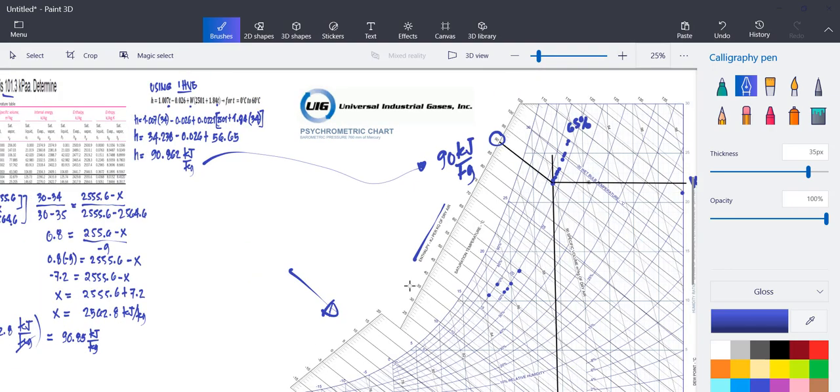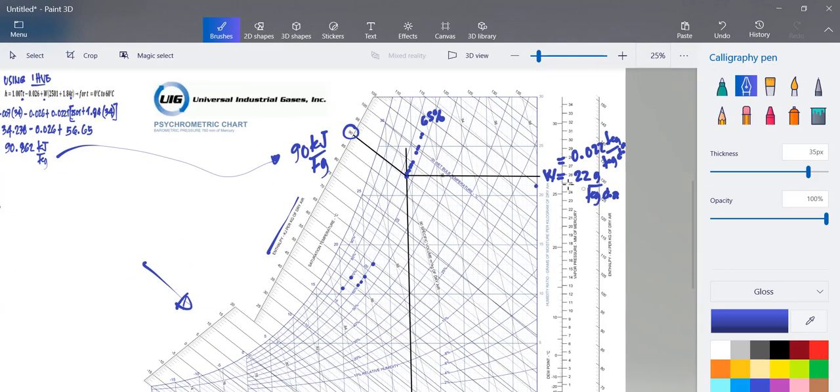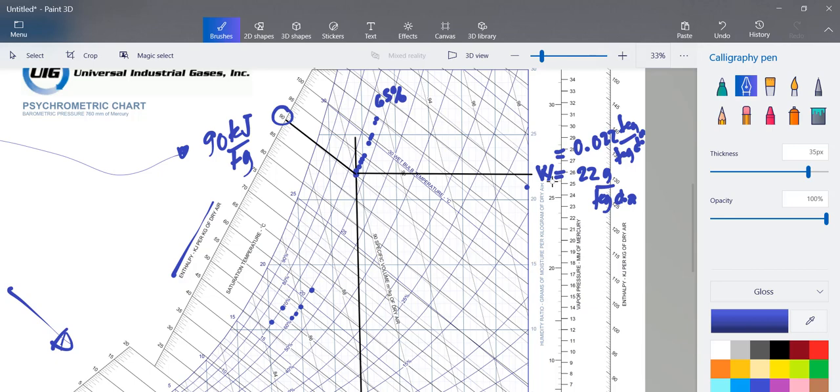So you will notice, no class, how efficiently we use the psychrometric chart for what we have been looking for. Then we have now your humidity ratio. So the corresponding wet bulb, you will see that, we have your wet bulb here. So this line traversing going there is the wet bulb temperature. When you pass this, this is now the saturation curve. Okay, and this is the enthalpy.